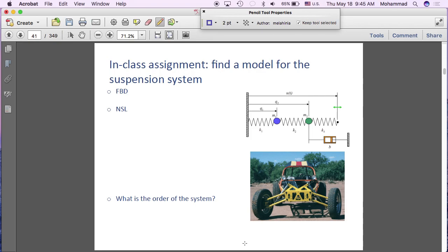So there is a source of displacement, which would be the roughness of the road. So the source of displacement change is shown here with this double arrow. So it could basically get closer or get farther away. We have one stiffness element, one energy storage element. Again, this could be the tire. This is the energy dissipation that happens through the tire. Then this is the actual spring.